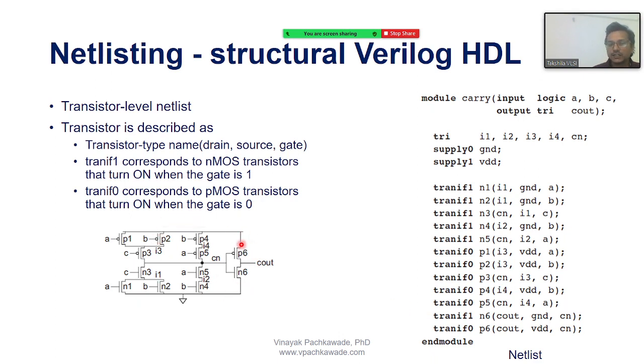Sometimes the physical engineers can also have access to the schematic. For example, it is shown here a particular circuit for a specific logic, or they can be given just a netlist. So they should be able to understand what this netlist means, what the lines are, and what the syntax is. It's just a code. So I explained to you how to understand this netlist.